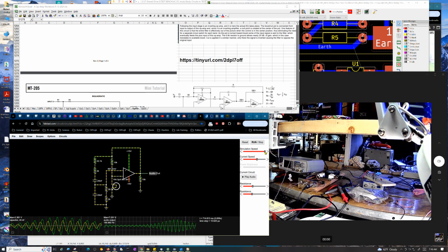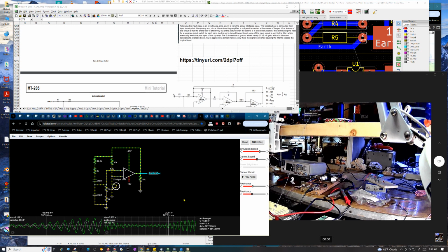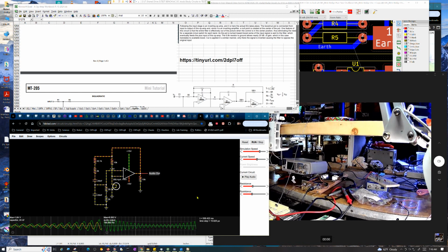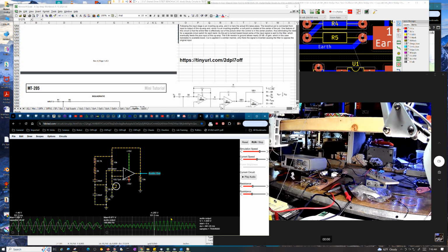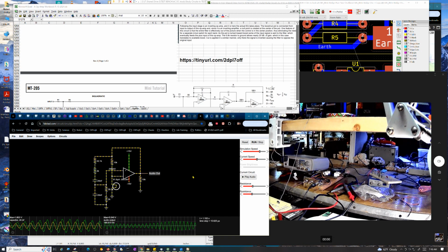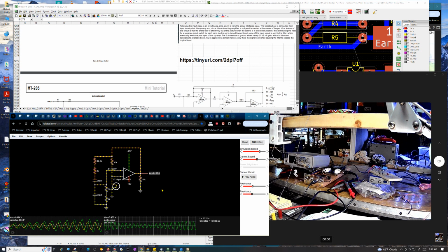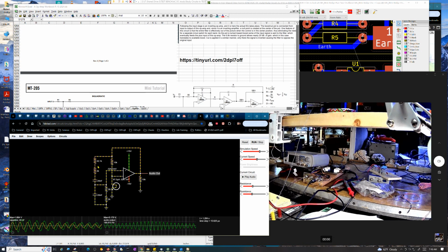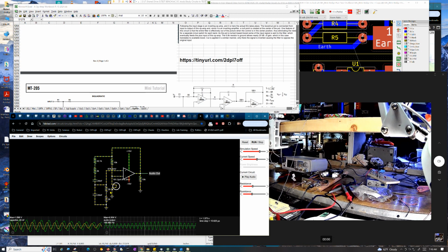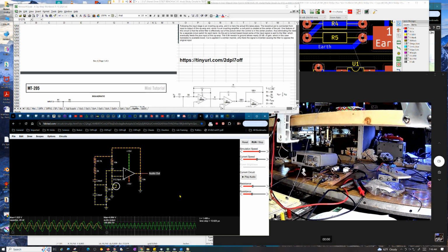You can try to run it at a higher rate, but it's having a hard time. But it does eventually start to oscillate. So just fair warning, if you want to play with the circuit, you may think it doesn't work at first, but give it some time. Let this thing zoom in and stabilize. Even though I don't have the resistors matched here, you can see they're slightly different. That's 42K, and this is 39K or something. But it shows you this thing can oscillate under various conditions.